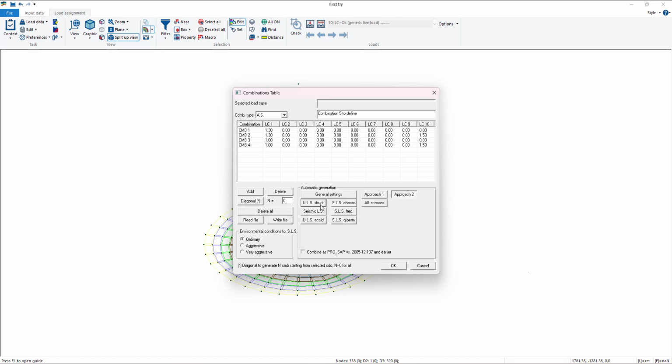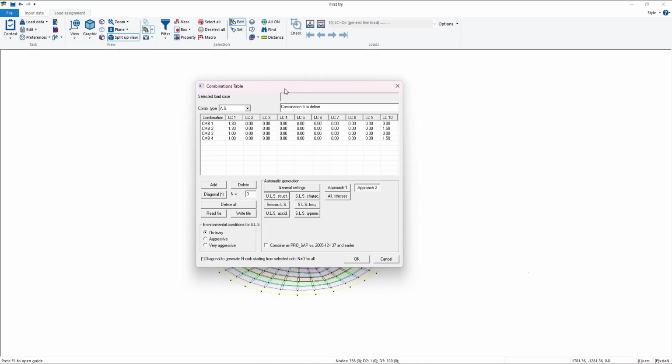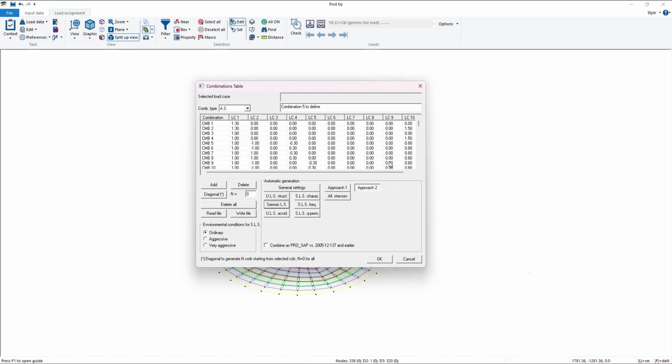So here we have structural. With structural we have normal load combinations that do not include seismic actions. For that I have to use the seismic load state, and the software automatically creates combinations using the 100-30 rule, in which each time we apply a seismic load on a direction, it's also applied 30% of the load on the orthogonal direction for every combination possible, basically.